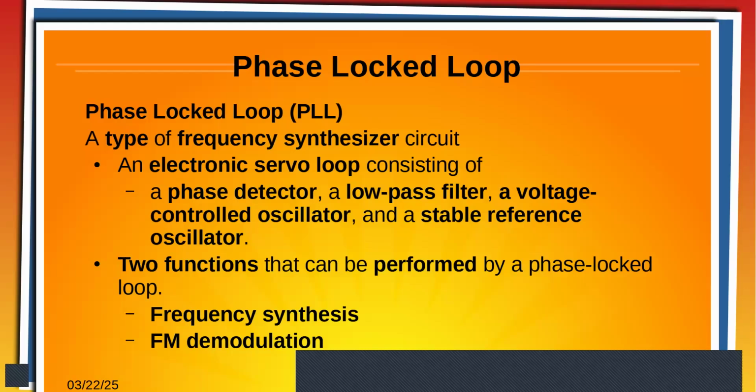We use it here to calibrate it, because you can calibrate the frequency by adjusting that offset to zero and get it accurate to within a fraction of a hertz. Very accurate oscillator. Yeah, temperature controlled crystal oscillator.